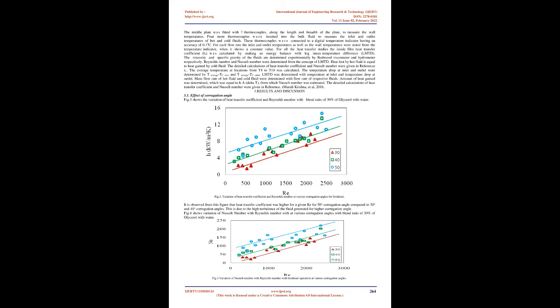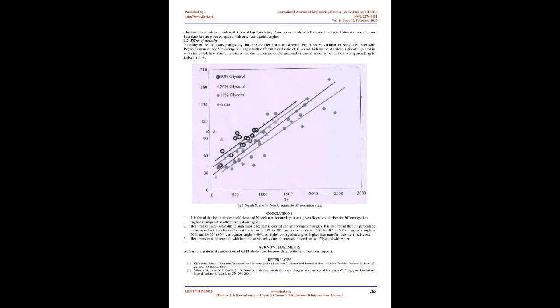Thermal and hydraulic characteristics were evaluated using analytical solutions for the entrance and fully developed regions of a sinusoidal duct adapted to the basic single cell. The derived correlations were finally adjusted so as to agree with experimental results from tests on channels with angles equal to 8 degrees and 65 degrees. f and Nu calculated by the presented correlations were shown to be consistent with experimental data from the literature at Re equals 210,000, angle equals 67 degrees, and B/L equals 0.26.